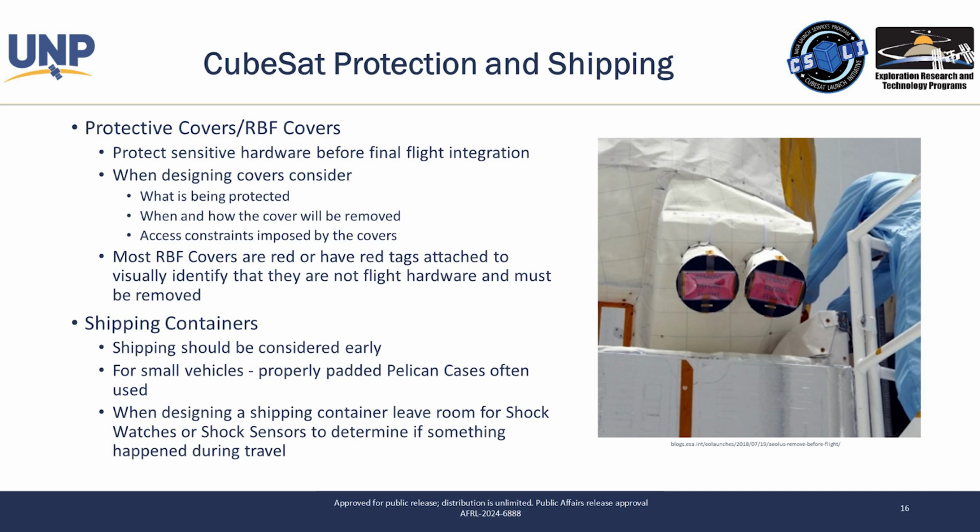You either have to find a van or ground transport or air transport that's dedicated to you in that case, or plan for shipping, which FedEx can do, but it is expensive. Important whenever you are transporting the system to have shock watches, which are sensors that will trip if it experiences a shock of some magnitude, to know if the FedEx guy just chucked your $1 million satellite off of the loading dock, which does happen, or even if you accidentally bang it on the door of the airplane when you're carrying it, that can cause damage to the system within.